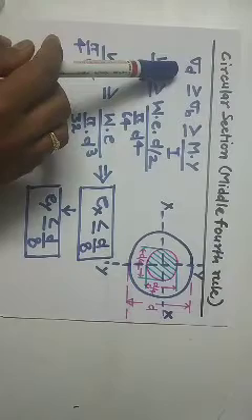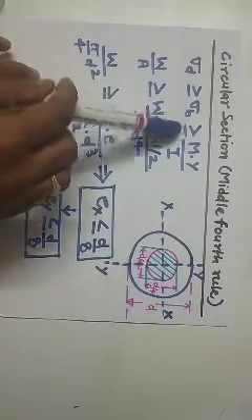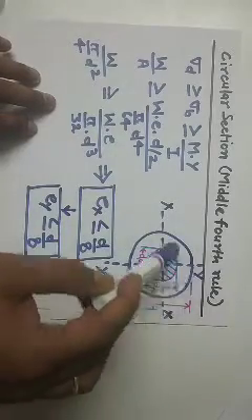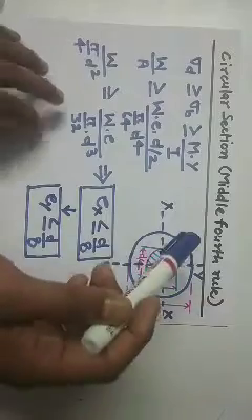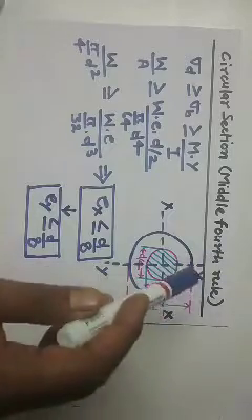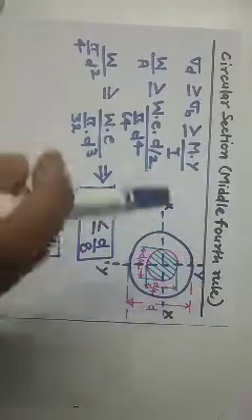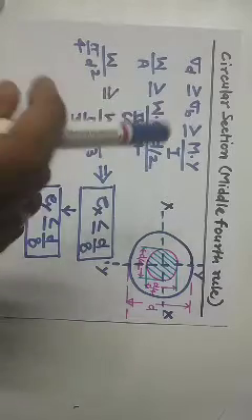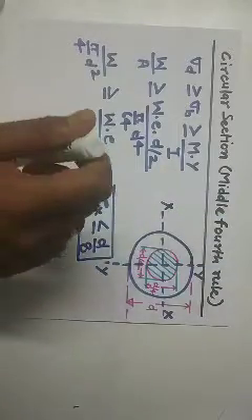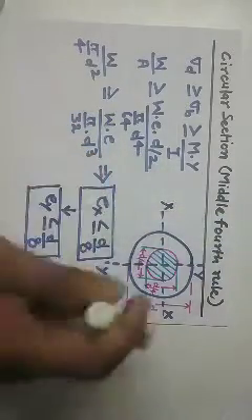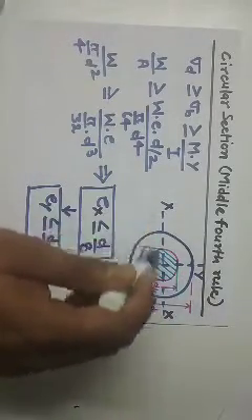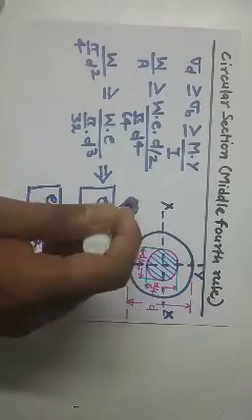Say, for the condition of no tension, sigma d will be greater than or equal to sigma b, which is M into y over I, because there is symmetry in the section. IXX is equal to IYY, so no specific attention is needed on whether the load is placed on the x-axis or y-axis, because IXX is equal to IYY. But in case of a rectangular section, be very clear: when load is placed on the x-axis, then MOI will be taken about the y-axis, and when load is placed on the y-axis, then MOI will be taken about the x-axis. But here in case of a circular section, there is symmetry in x and y, so no such specific attention is required, right?